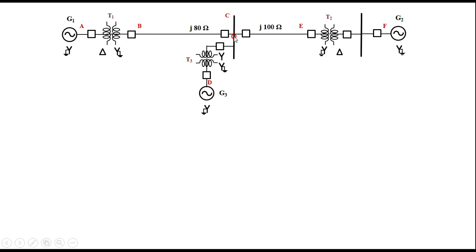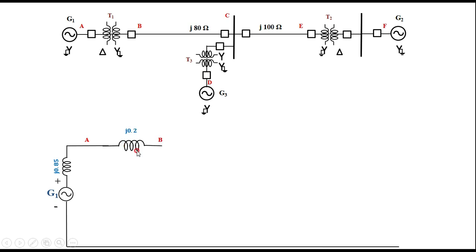Then once you have calculated, you have to draw the reactance diagram. Here I have mentioned 2 lines. Then there are 3 generators G1, G2 and G3. They are the extreme points of the network, starting from the ground. The same basic principle you have to follow. Therefore you can see here, this is the ground line which I drew first. Then first G1 you can start, it is represented by source and reactance. Then point A here. Then transformer T1, having point 2, this is point B.